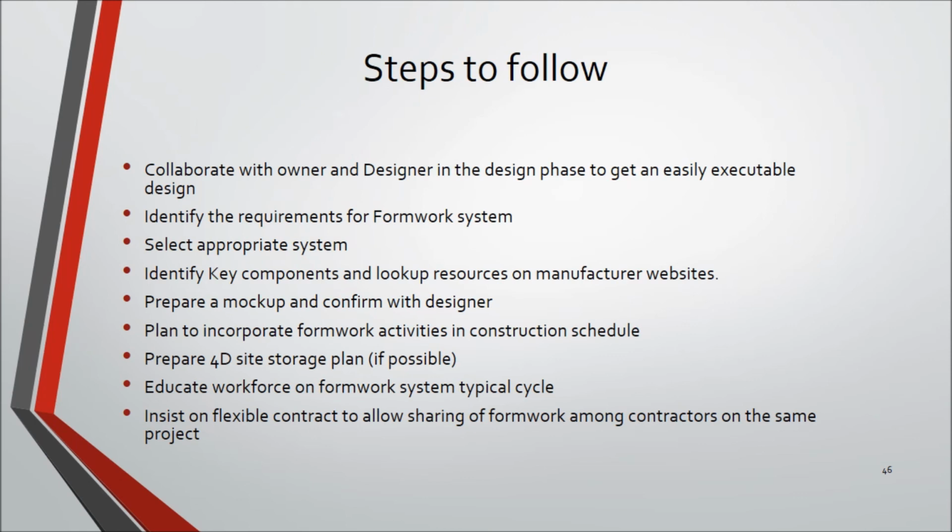Eighth, educate workforce on formwork system typical cycle, and inform about the safety features of the system. Ninth, insist on flexible contract to allow sharing of formwork among contractors on the same project. That is it. These steps will ensure a high productivity of your formwork system project.